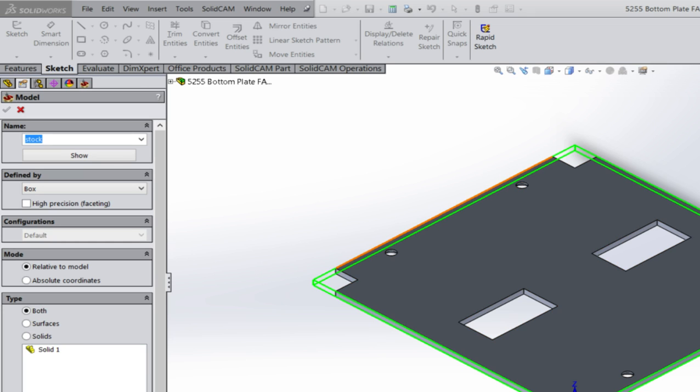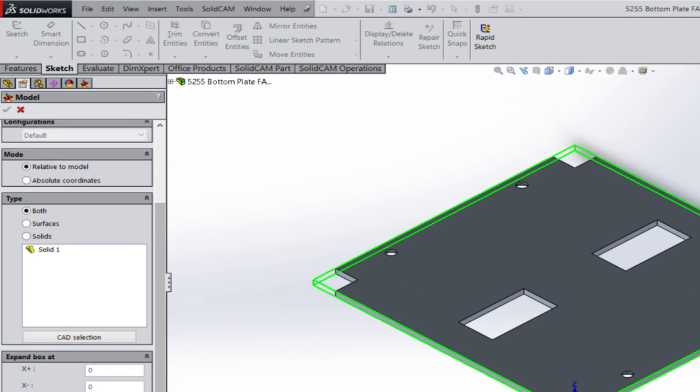Would I bandsaw it exactly that length? No, because I can't keep the bandsaw perfectly parallel and straight, and it's got rough edges when it's done. So we want to bandsaw it bigger than this piece. So what you should do is bandsaw it and then measure what you have left. So I probably would have bandsawed this and tried to leave at least a 1/16 on each side.